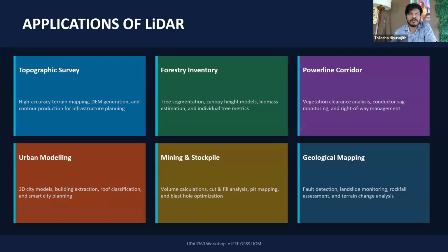When it comes to planning a city in a proper way, you might have to consider how sunlight radiance and its occurrences are affected by buildings and tree assets, and everything needs to be considered when you are planning a city. So in such cases, you have to derive slope, aspect and irradiance parameters accurately. You can do it to some extent using 2D geospatial data, but with 3D city models, you can do it with the maximum accuracy that you can achieve.